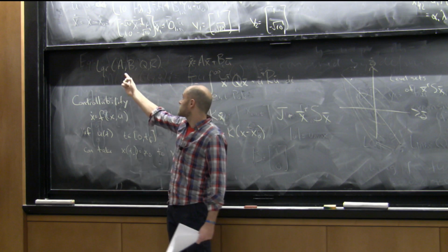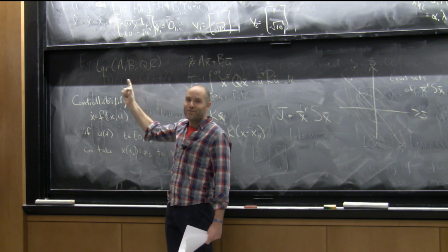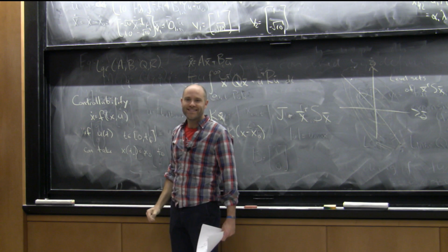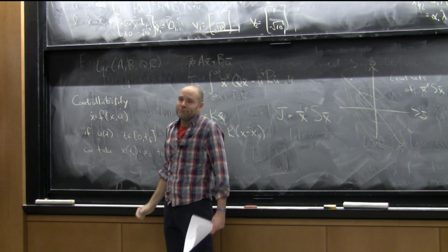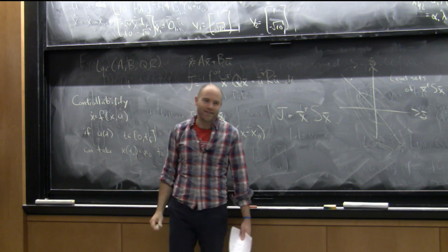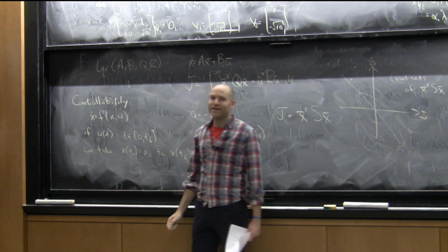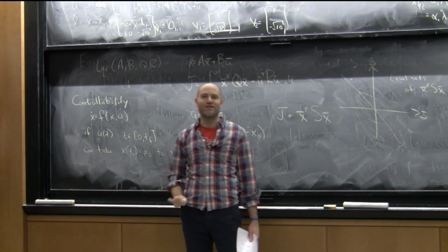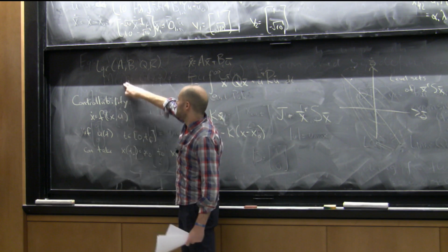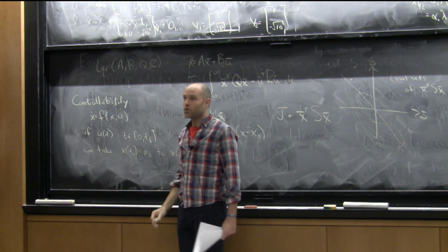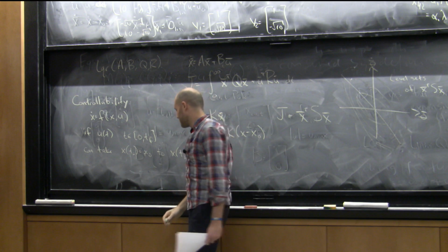If it's possible, if it's controllable. Now, the advanced fact is that not every stabilizing linear controller can be found by calling LQR with some Q and R. So, if you had some controller out there you're really hoping to get, searching over Q and R isn't guaranteed to find it. There are other parameterizations that do have that property, which might be better if you're just trying to do a brute force search over controllers, but this is pretty good. I mean, in practice, everybody uses this because it's how you can make robots work.